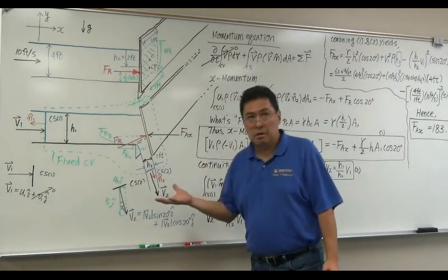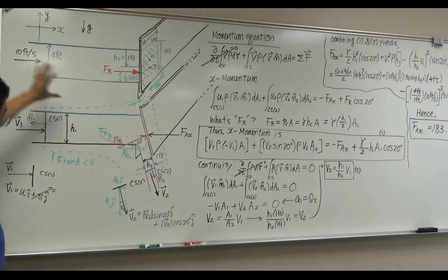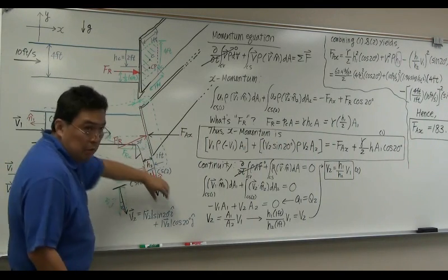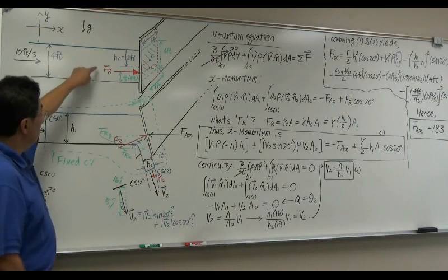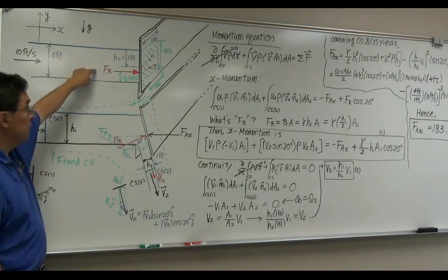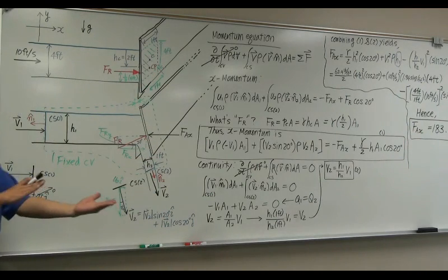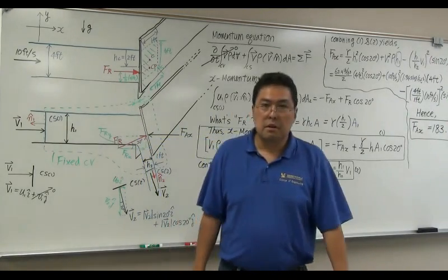This is not an easy problem. We need to all understand what causes this plate turning and then the water escaping out from this gap. What is the mechanism? The mechanism is the hydrostatic resultant force developed, which is really pushing and keeps pushing this plate to open the gate. This is quite a challenging problem.